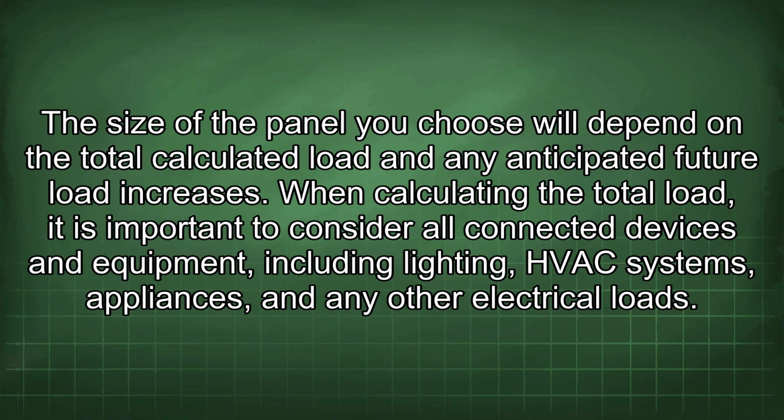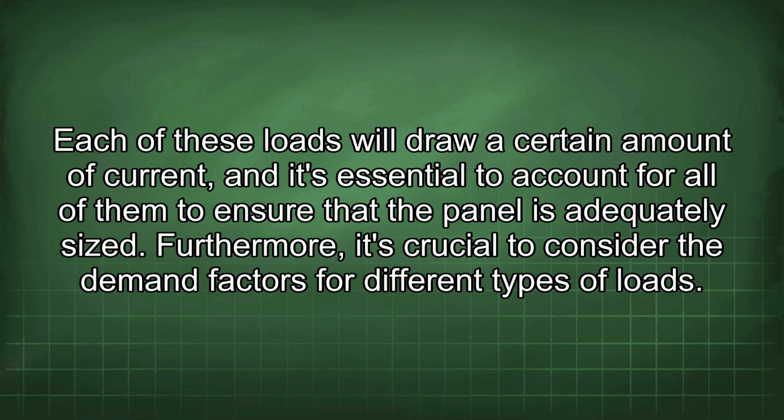When calculating the total load, it is important to consider all connected devices and equipment, including lighting, HVAC systems, appliances, and any other electrical loads. Each of these loads will draw a certain amount of current, and it's essential to account for all of them to ensure that the panel is adequately sized.